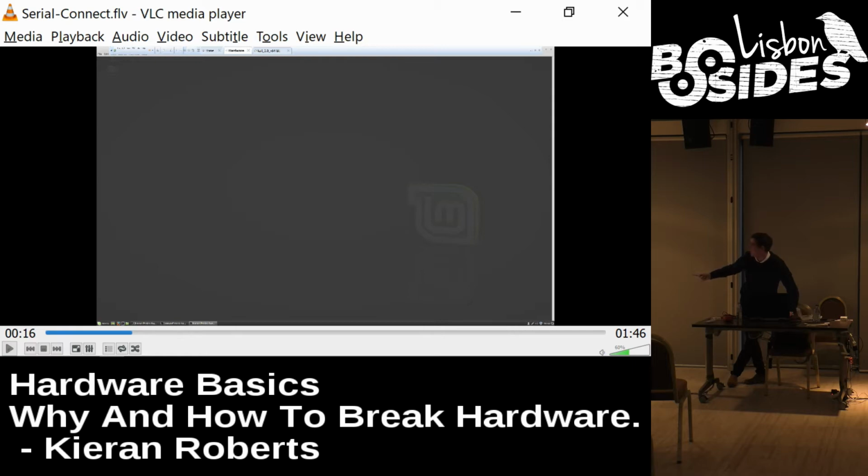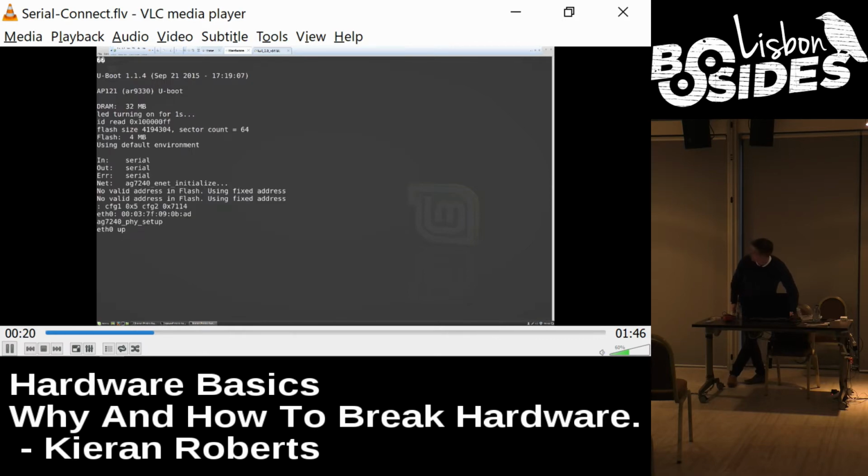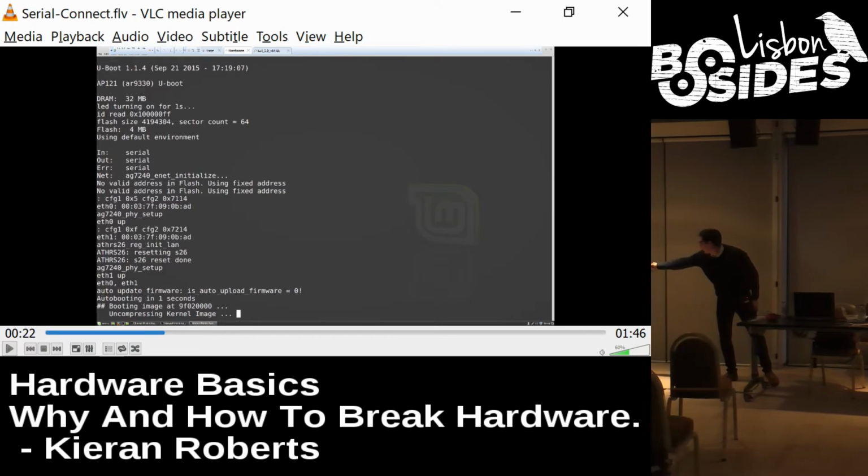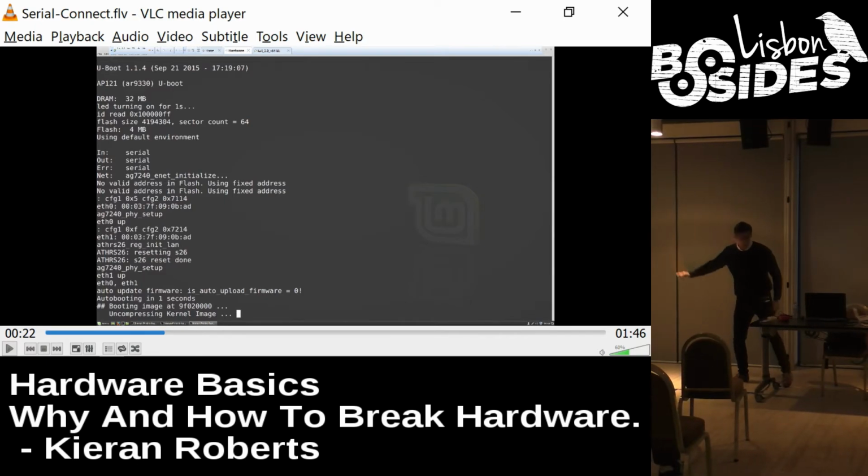There are a few different baud rates. That's probably the most common. There are tools out there, like baud finders, that will try and brute force it. If you get the wrong baud rate, you'll just get garbled output. Nothing bad is going to happen. So see here where it says at the bottom, auto booting in 1 second. That's relevant later. We'll come back to that.